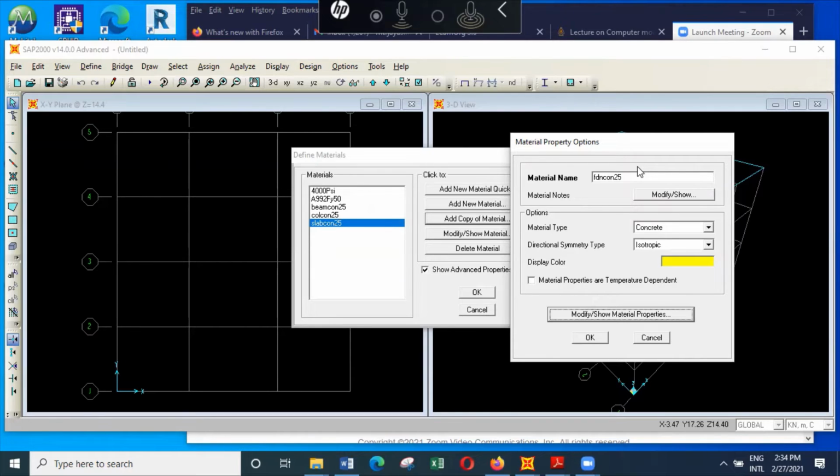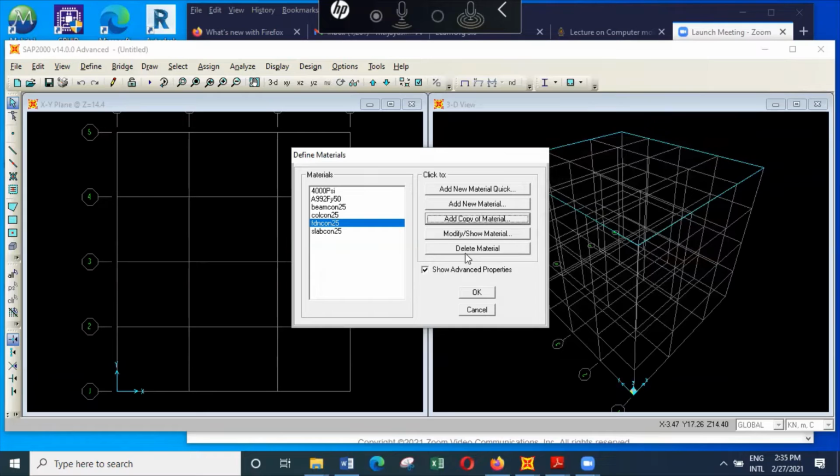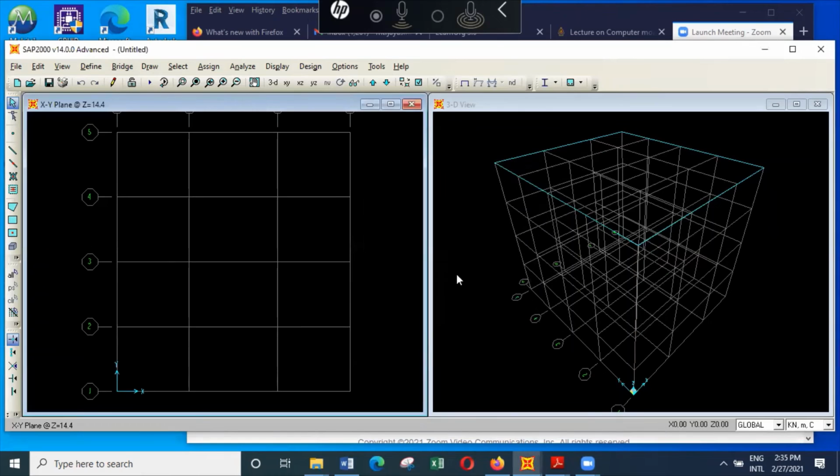The reason is when the foundation is laid, its self weight is supported by the soil underneath. So the load is resisted where it is applied. Because of that, due to the self weight of the foundation, we don't get any bending moments and shear forces. So I can say the foundation concrete is also a weightless material. It has no weight. So I can say okay, and we'll just keep the rest as it is.